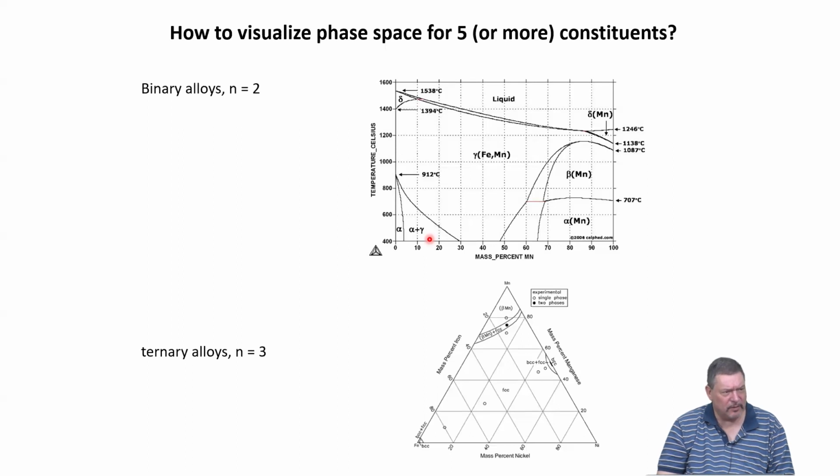If we have a ternary alloy, obviously we have already a difficulty because we have three components and we have temperature in order to get the same information into our diagram. So the diagram would be a trigonal prism. It would be a prism which has three sides. And the temperature axis would point up as the long z-axis, and this would be in the xy plane.